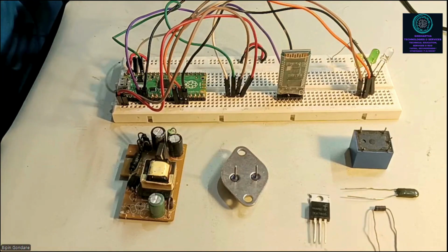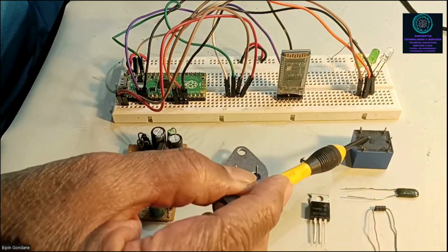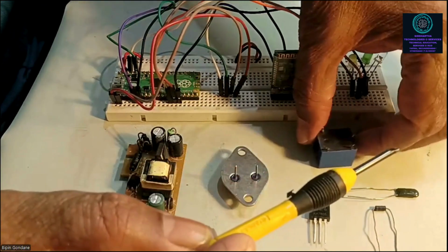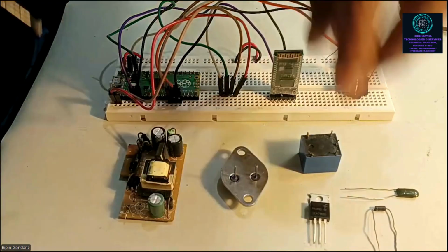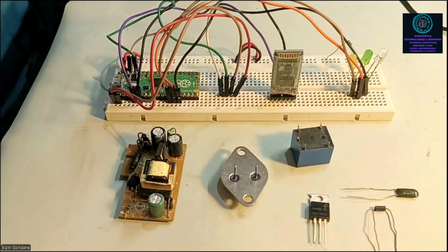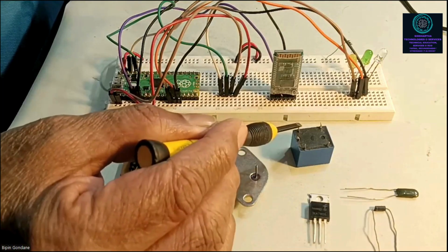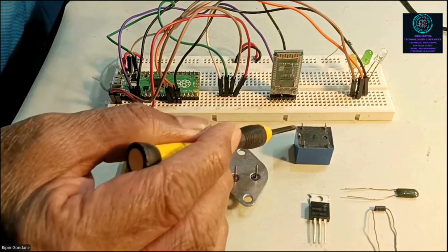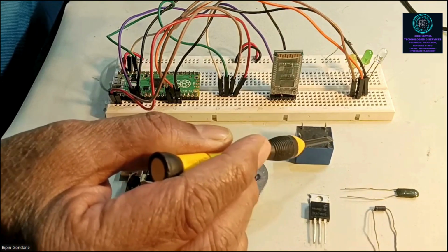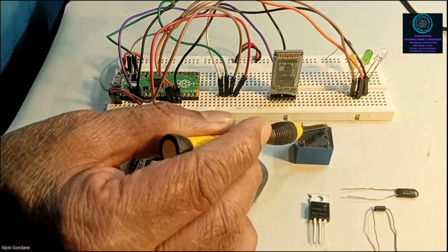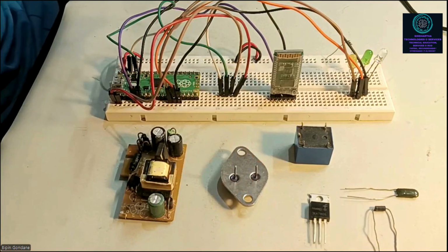Okay. The second point we have discussed. This is a relay. So the relay has how many points? It has 1, 2, 3, 4, 5 points. So where to connect what? I will tell you by looking at it. These 2 points are the coil points, and this is the common point. And one is NO and one is NC. Just now we saw in the previous part where NO and NC are.